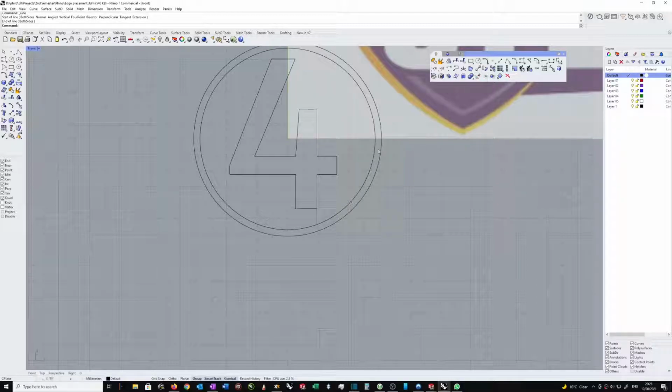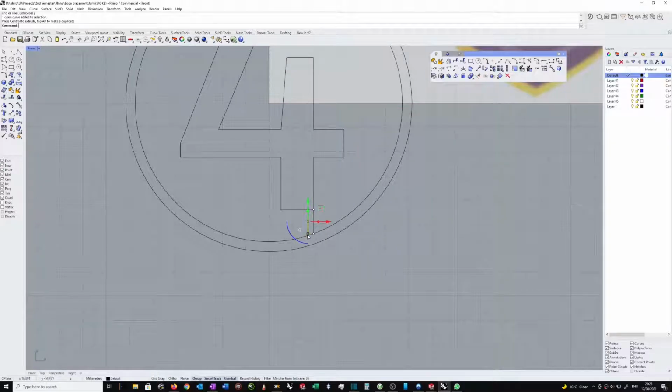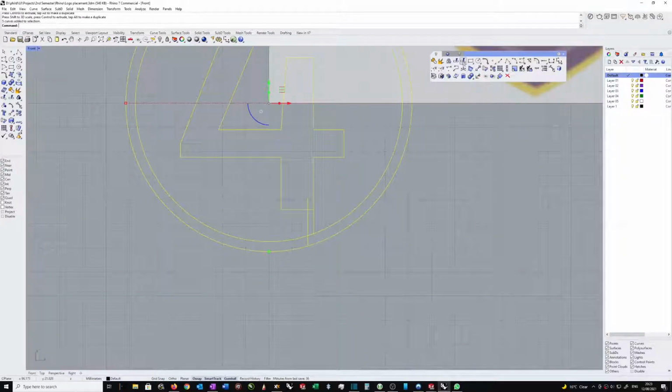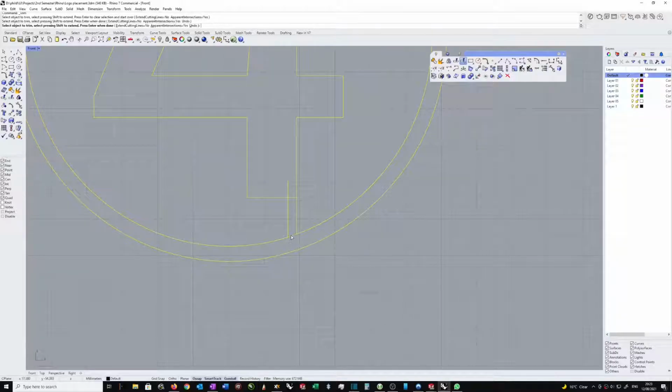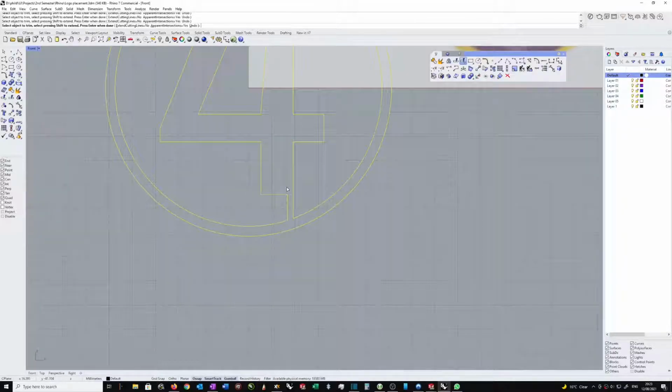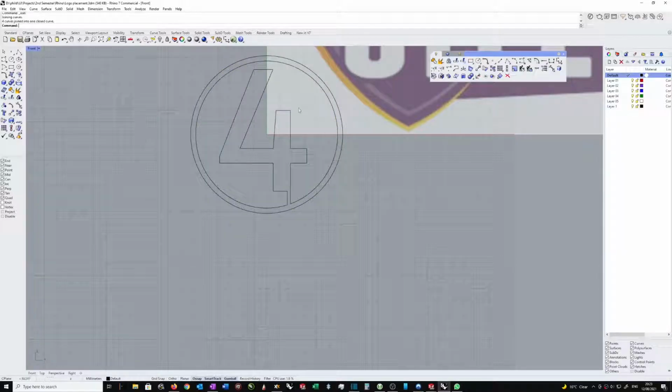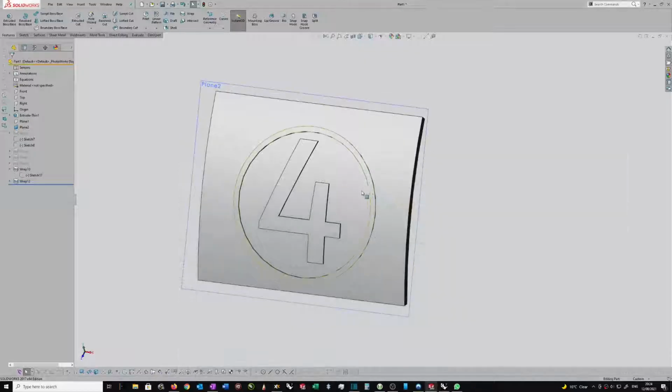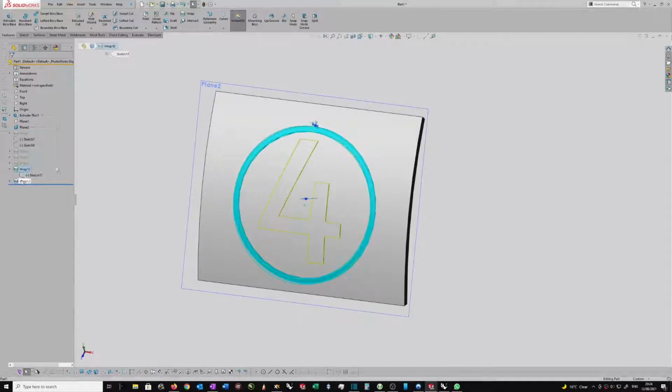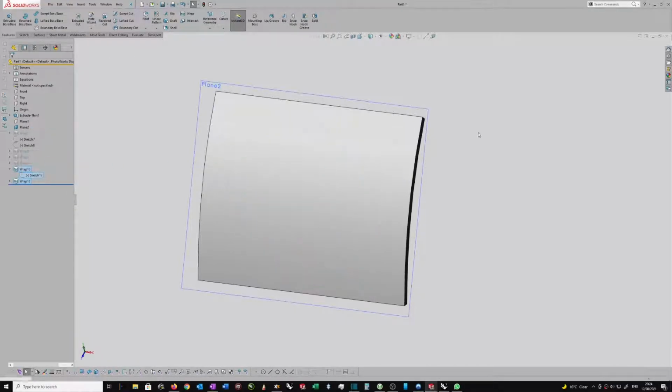So I create a line, I create a duplicate of that line. Right, these two, I just need to chop off the bits that I don't want so that there's some sort of bridge between them, like that. Join them. Okay, and I've already made this, so I'm not going to do it again as a DXF, but I would select this, send it through as a DXF, and let's just suppress these two and pull that in just to see what it looks like. So insert DXF, and it would be this bridged.